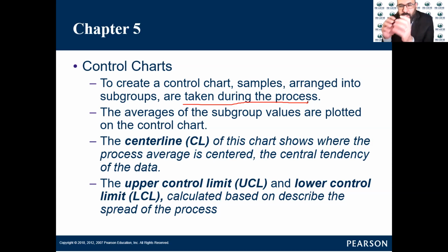What is important here is that you cannot take only a few samples and make a judgment on the whole process being out of control. You have to do at least 3 measurements for each sample.